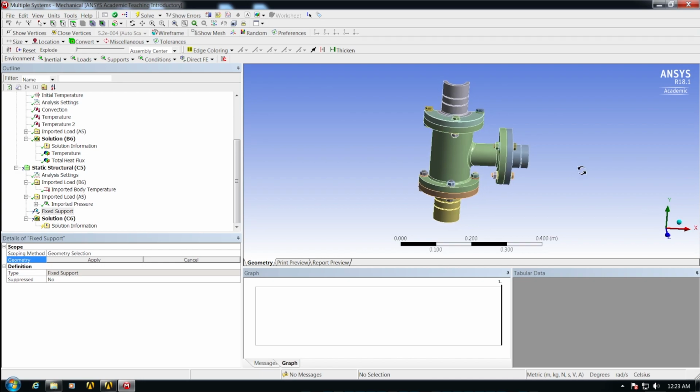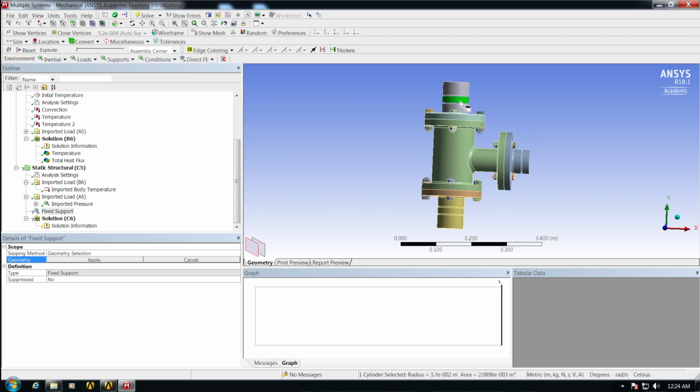We're going to rotate my pipe around. Now there are three areas on the pipe that we've created for where the supports, imagine them as effectively bands, are connected. First one is on top here, then Control-click the second one on the bottom here, and the third one is this far lip on the right. So after you Control-click those three surfaces, hit Apply, and those are your supports.